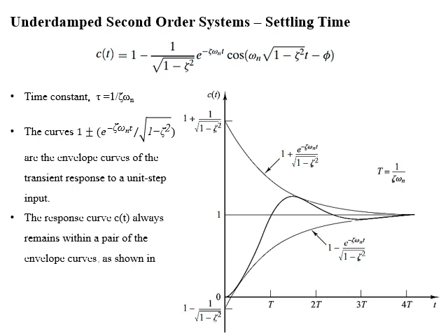Dear students, now we will find the relation for settling time using an alternate method. We have the equation for the time response of a second order system whose time constant equals 1 over zeta omega n. The time constant defines the speed or rate at which the response of the system responds to changes.